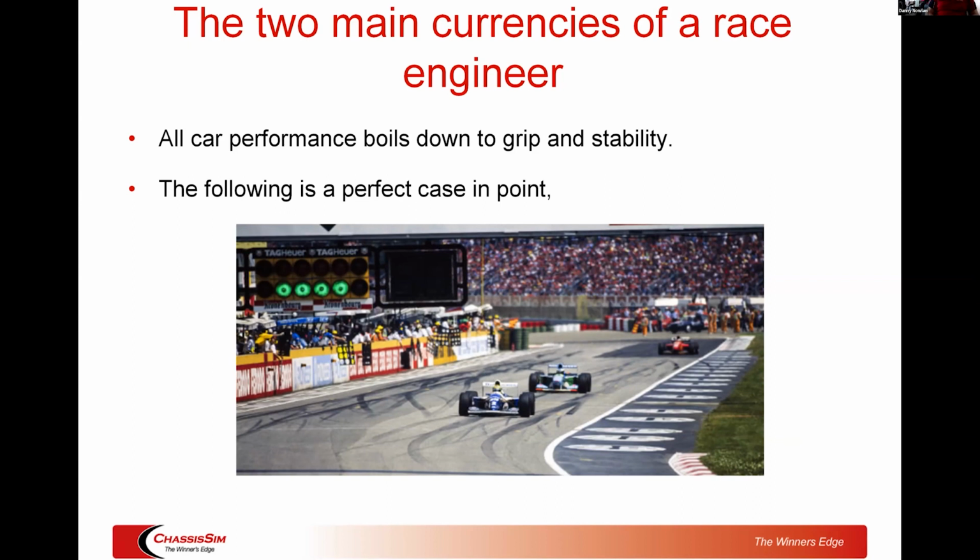But here's the thing: that car, that blue car there, had been designed for active suspension. What that meant is the aero only worked in a very, very narrow band of ride height. So in August 1993, the FIA, in their so-called infinite wisdom, decided to ban active suspension. So you had what was an active car all of a sudden being thrust into being a passive car. And so this was a car that had incredible Jekyll and Hyde handling. Indeed, Ayrton Senna's race engineer David Brown once said that for the first 3 races of the 94 season, the Williams wasn't on pole, Ayrton Senna was.